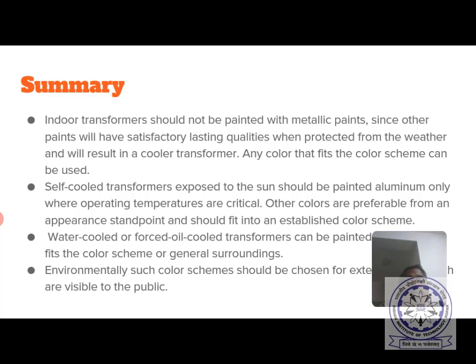Then, as a summary, indoor transformers should not be painted with metallic paints, since other paints will have satisfactory lasting qualities when protected from the weather and will result in a cooler transformer. Any color that fits the color scheme can be used. And self-cooled transformers exposed to sun should be painted in aluminum only, meaning metallic paint only, where operating temperatures are critical. Other colors are preferable from the appearance standpoint and should fit into an established color scheme.